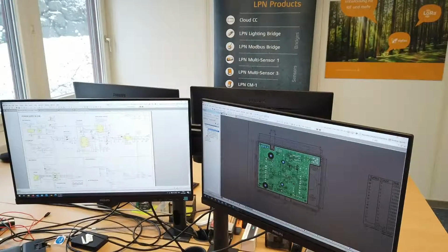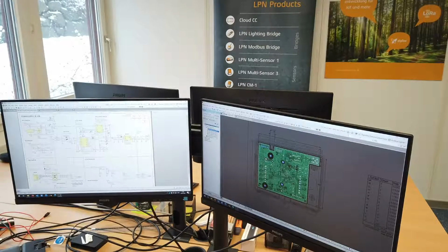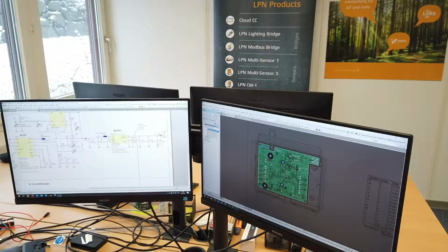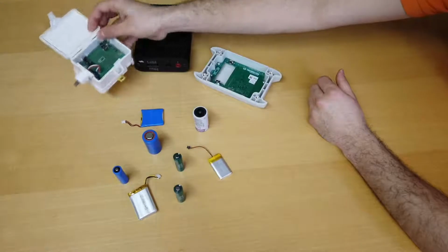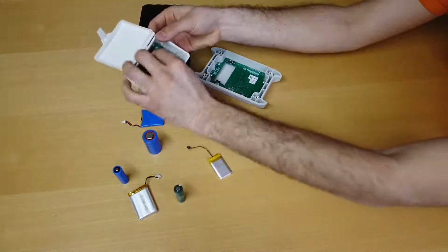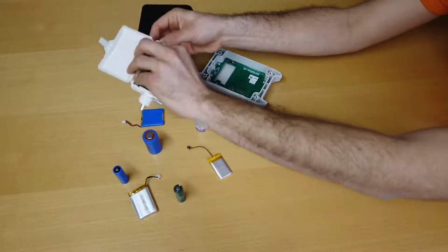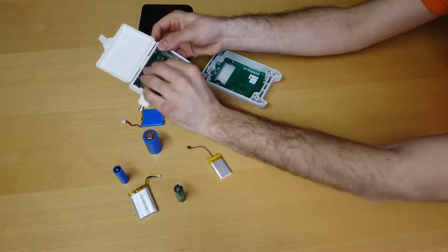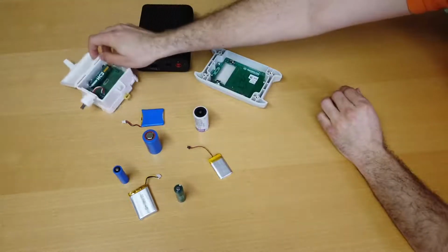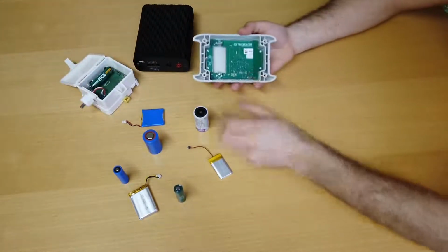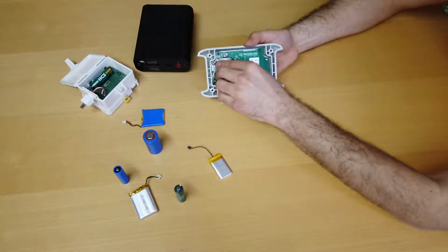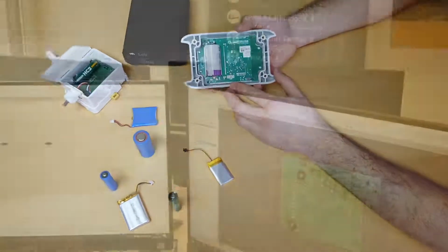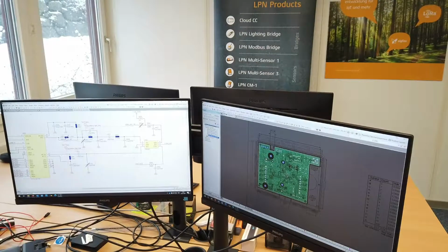We recommend you guys to calculate and build a device consumption profile as precise as possible. Take as many variables into account, like battery self-discharge, temperature profile, and so on. It is important to know that not all batteries are suitable for all products, so it is important to look at that. Take care about not only looking at the datasheet, but also making measurements with the battery, discharging them, or for example, try to simulate them.